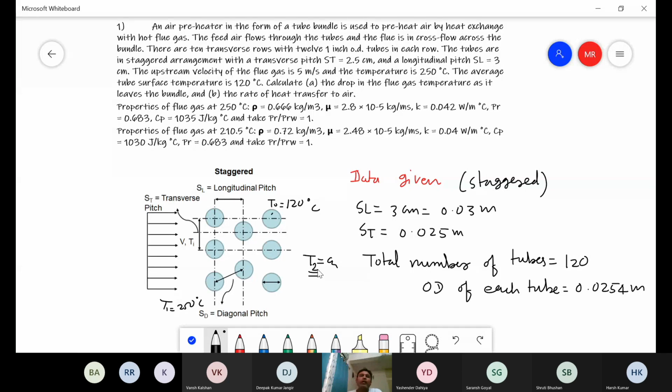We continue until the outlet temperature we have found and the outlet temperature used for calculating the properties of the flue gas become the same. So these iterations have to be performed several times till there is a match between these two temperatures.